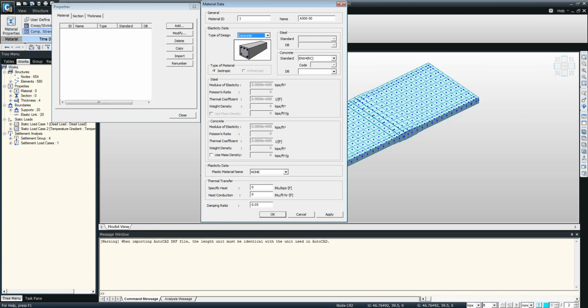There's a question from Russell Jack. It's a very interesting question. The question is, when analyzing a composite bridge, one of the techniques is to model the negative moments as steel only and the positive moments as composite, since the area with the highest moment of inertia will attract the greatest moment. How does Midas do it? So let me reframe this question.